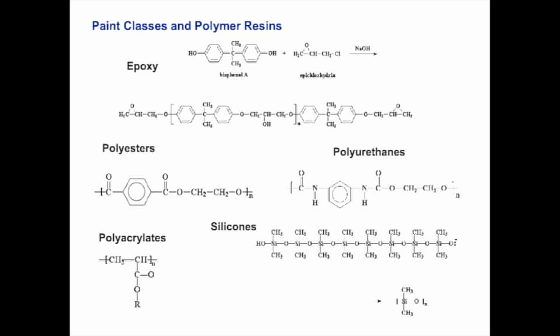And of course, those who have worked with epoxy paints know that along with the epoxy, you need a hardener. A hardener, usually an amine, provides the cross-linking to produce a thermoset paint that is a protective type of coating. Other types of polymers could be based on polyesters or polyurethane. Again, polyurethane can be a thermoset or it can be elastomeric based on the hard and soft segments, or rather ingredients. And then you can vary the polyurethane chemistry by changing the polyol or the isocyanate type of ingredient.